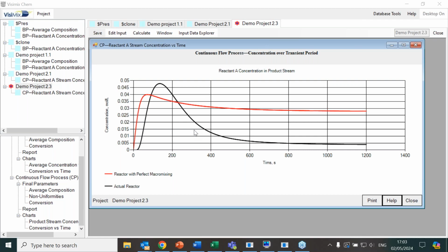Hi, Amando, to hear your question. Thank you for the presentation. You talk about macro and micro mixing, but what about meso mixing, intermediate eddies or in the feeding zone? As you can see, we are taking this into consideration. The second example that I showed you was very fast, but I showed you a different feeding position. So we know about the feeding position and its influence in the tank, not only because of the macro mixing movement, but because the drop that's entering there is experiencing some diffusivity and some eddy size and Kolmogorov eddies that will influence the local interaction.